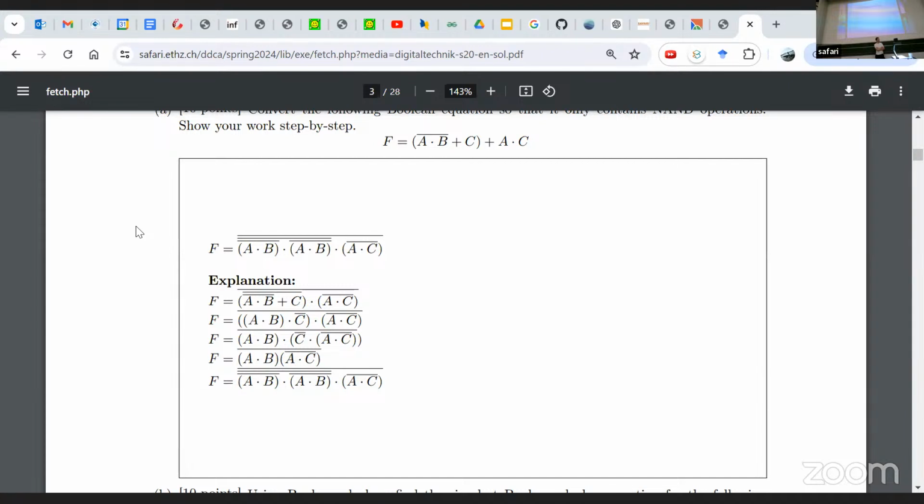And you can disable the flip-flop, so some input comes here, he's just not looking at it. It's just like you put a blind in front of the flip-flop, he opens his eyes, but he sees nothing, or he sees the previous input, and he thinks nothing has changed. So that's what you use for stalling. Okay, so you physically stop the propagation of the data by disabling the flip-flop.